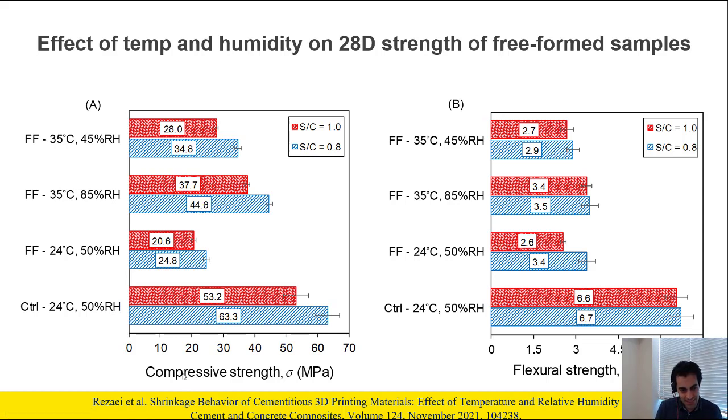So you can see that those free-form conditions actually don't allow the material to get hydrated, which is very important during that first 24 hours. And you can see the differences here. Especially when we got the lower relative humidity and lower temperature, you can see that the difference in terms of the strength is massive compared to the environment where you allow the material to get cured inside the mold for 24 hours.